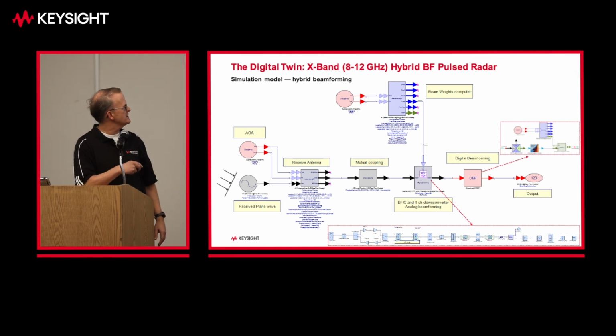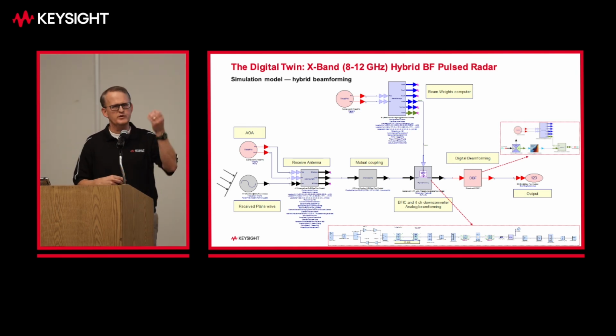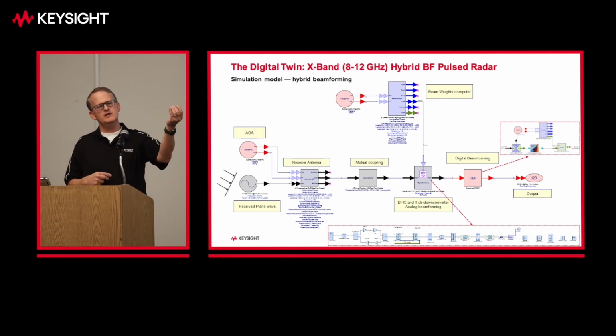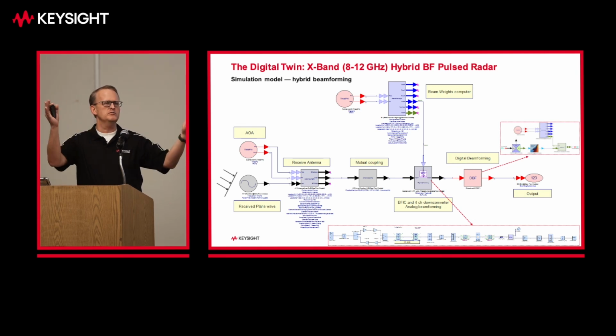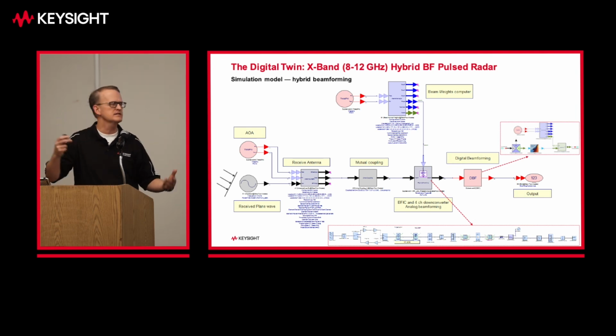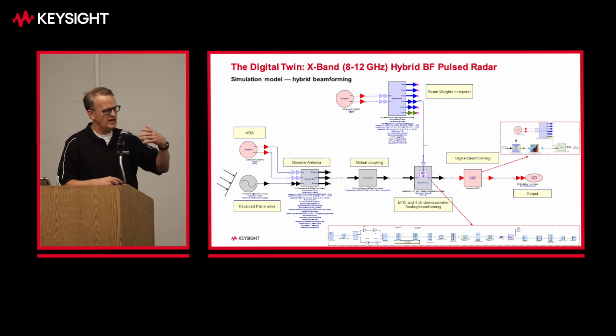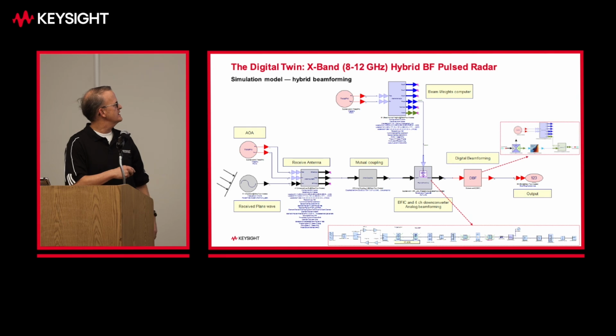On the analog beamforming side, we have a model here. I'll get into this in a couple slides, but it'll take in real EM simulated data from ADS, from HFSS, or even range data from your far field measurement in your antenna range or a compact range. You could put that data in there per element. There's a lot of configurations, and even a coupling matrix, so it's very accurately modeling the antenna. And then we can even model things with S parameters and mutual coupling.